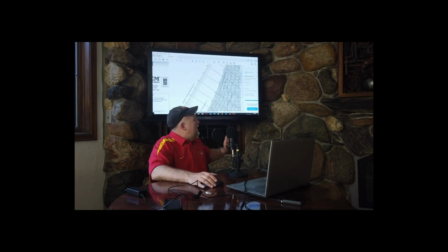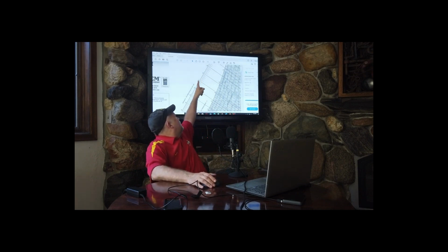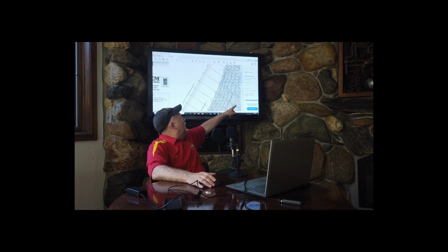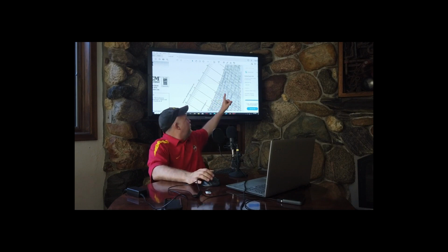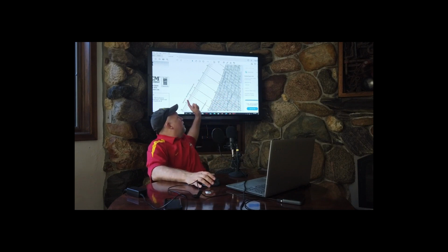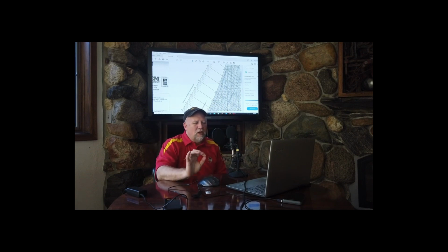Look over here on the right. These lines are enthalpy lines. Notice these go down. They're not quite parallel to wet bulb. They are really close, but be cautious. They are not quite parallel to wet bulb lines. But this is the enthalpy, BTU of energy per pound of dry air.